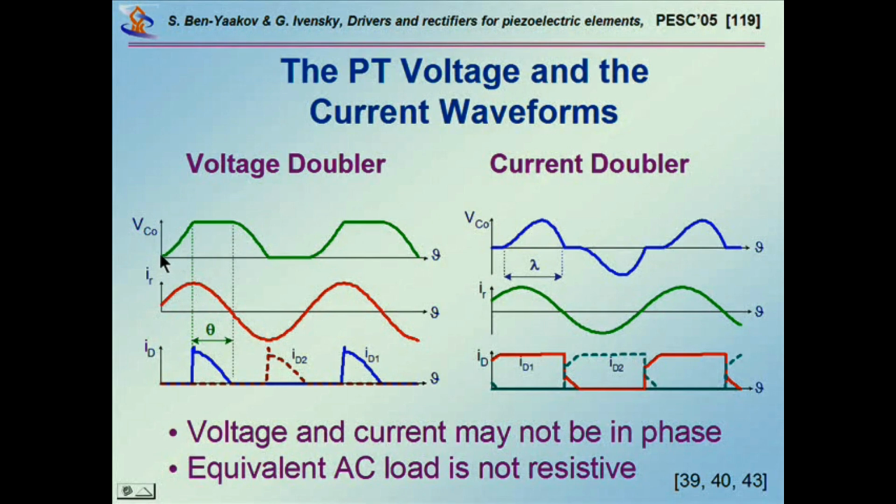So what you have to do is look at the first harmonic of this voltage and take into account the phase shift between this and the current, and this will be the power coming from the piezo, and then you translate it to the load.